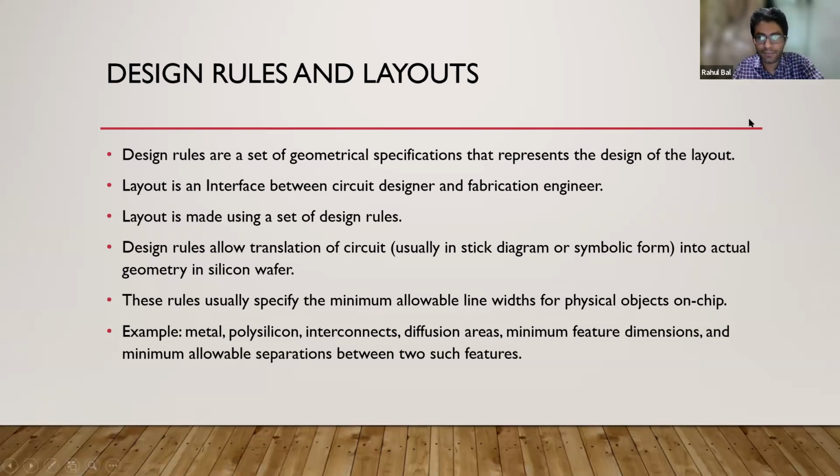So for example, just a minute, I'll annotate once again. So this is your chip, and this is NMOS, and this is PMOS. So what should be the distance between the connections of NMOS and PMOS? Whether we can place them like this, very near to each other, or what is the maximum allowable distance between the NMOS and PMOS. Such things come into the picture when you are talking about the rules.